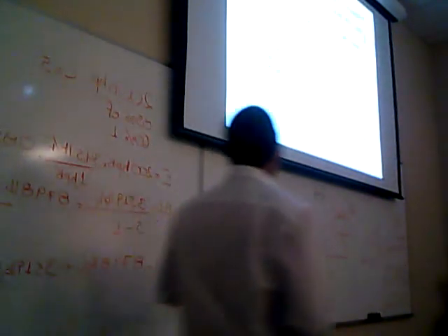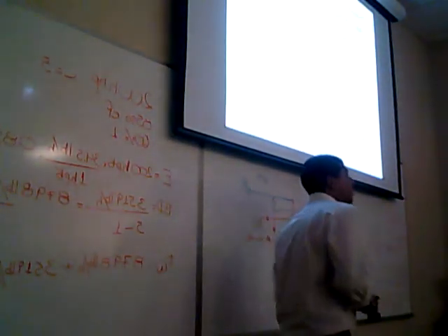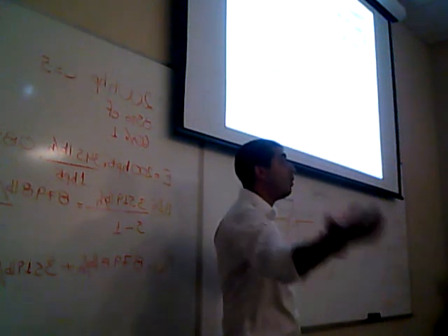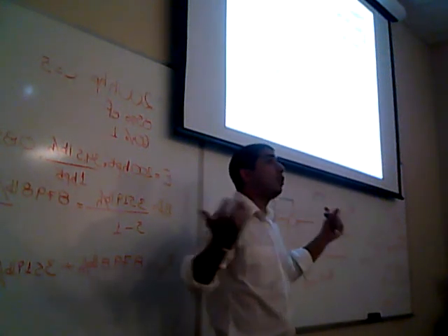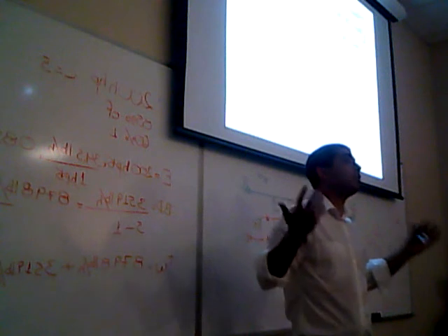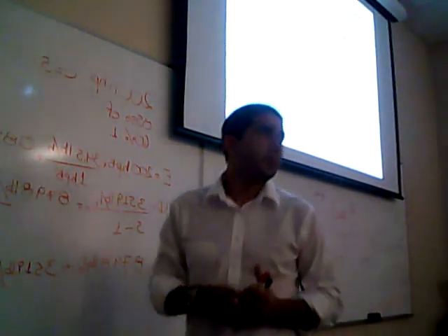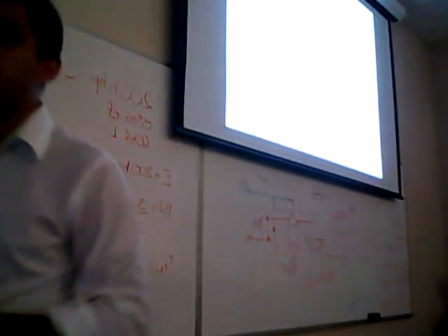What happens if the quality of the steam is low? You're going to have a lot of water in the steam, so you're going to increase the rate of corrosion in the pipe. There are three types of inspection for the trap: the visual, the thermal, and the acoustic.